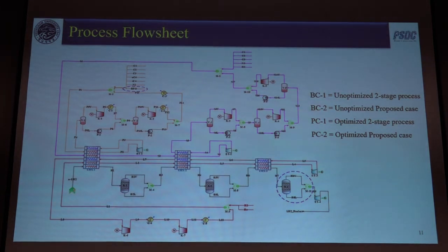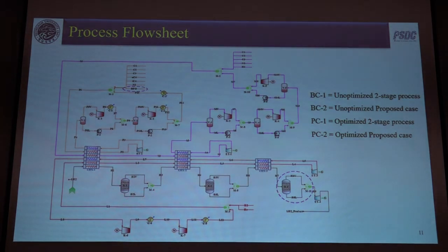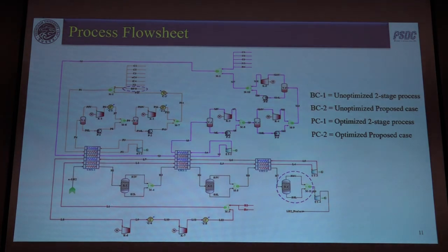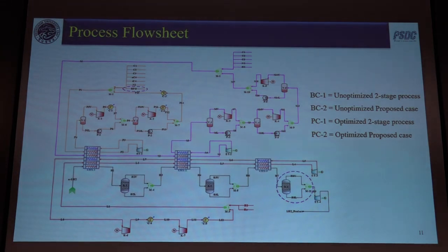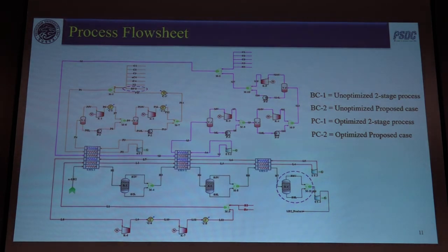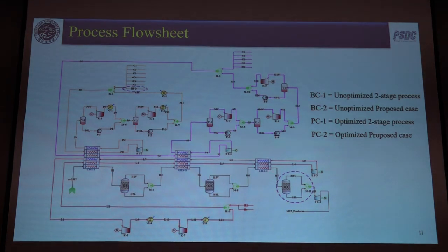So our cycle actually starts from hydrogen here, then we have the reactors, 3 reactors. So ortho is converted here, but only the equilibrium composition is considered. So at a given temperature, what is the equilibrium composition? Using the equilibrium curve that I have already shown, we utilize the data and have simulated the reactor to get the para-hydrogen concentration. At the end, we have around 99.5% para-hydrogen, which is actually the requirement for the industry. So the 3 refrigeration cycles have been used in this particular process.